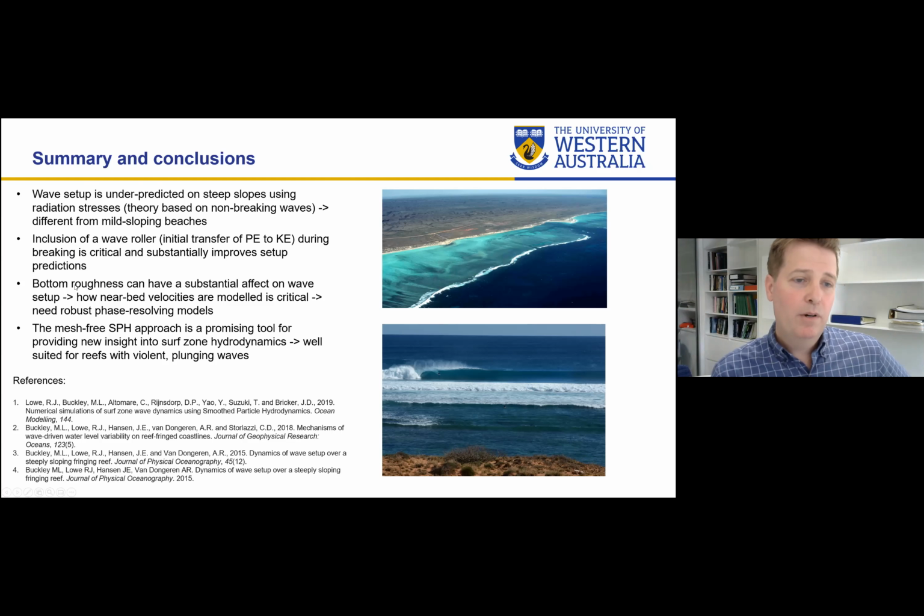Talked about how the bottom roughness has a substantial effect on wave setup. And if you look at this paper, there are quite interesting details. I haven't really talked about it, but how we describe the velocities interacting with the bed is very important. It really depends on accurately getting the wave shape right.